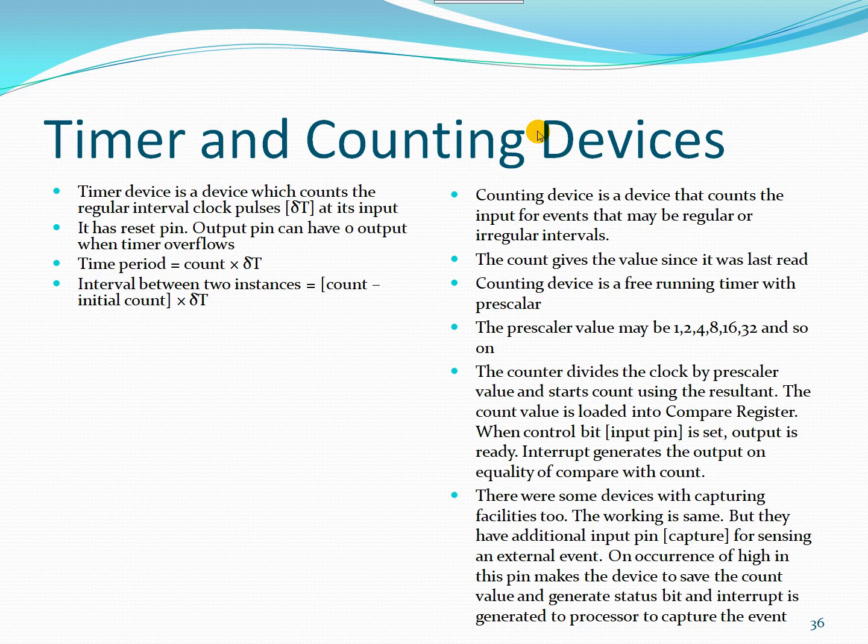So normally timers are mainly the inbuilt part of any microcontroller or microprocessor. In microcontrollers there will be dedicated timers for applications, but in microprocessors there will not be a dedicated timer for any application. But they will be having internal oscillators.